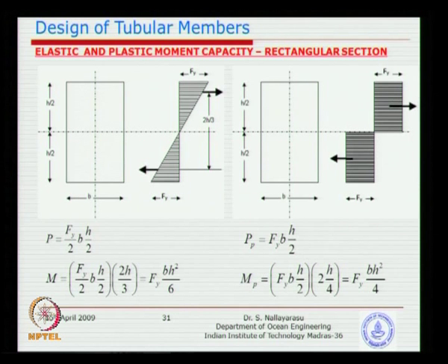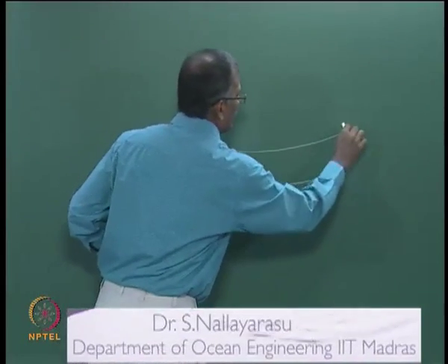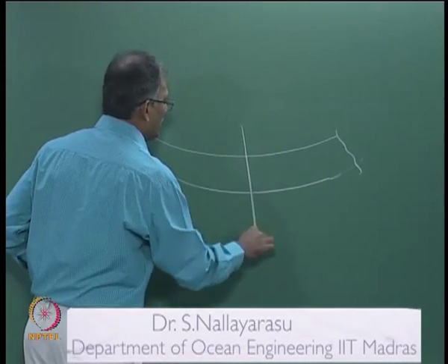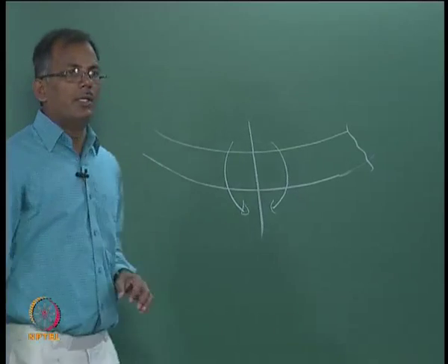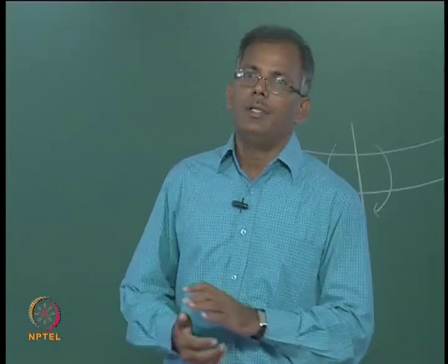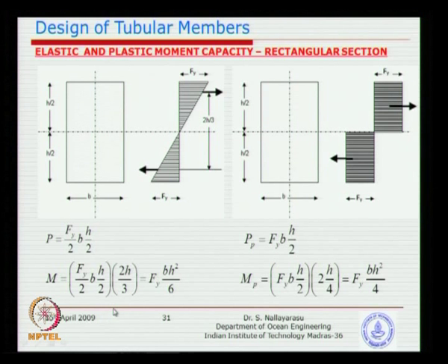This is just a beam subjected to bending, something like this. If you look at a long beam bending like this, and take one cross section at this place, your bending moments have to be in equilibrium. The moment produced by the beam internally is the force multiplied by the lever arm between the compression force and the tension force.